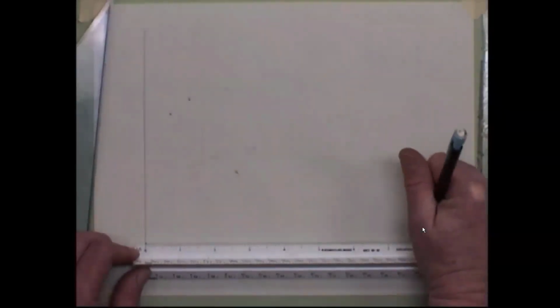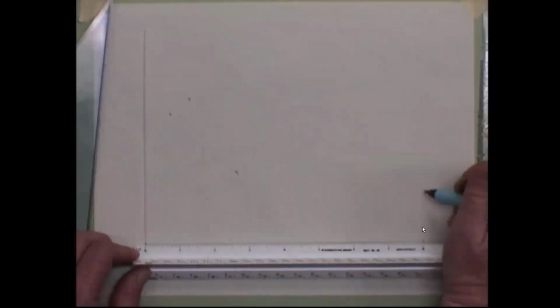You draw a line, put your scale up to it, and that distance, that width of the object was 8. And remember, single view drawings, all we see is width and height. And then the depth is given as a note. So we have 8 inches across here. And then our height was 5.5. So all I'm doing is putting my straight edge up to my line, measuring 5.5.